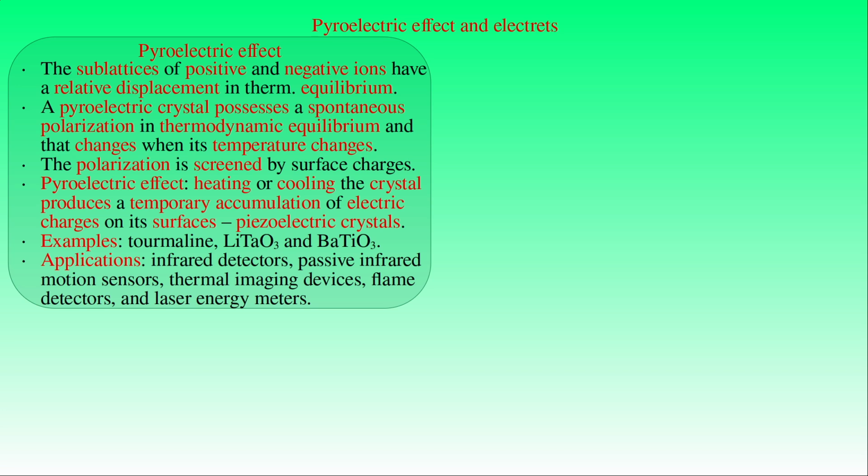Pyroelectric crystals are valuable in the manufacturing of thermal imaging devices as well, where they detect spatial variations in infrared radiation by converting temperature-induced changes in spontaneous polarization into electrical signals that form a thermal image. Another important application is in flame detectors, where they detect the characteristic fluctuations in the infrared radiation emitted by a flame and convert them into electrical signals for reliable fire detection. Pyroelectric crystals are also employed in laser energy meters, where the temperature rise produced by absorbed laser radiation is converted into an electrical signal proportional to the energy of the laser pulse.